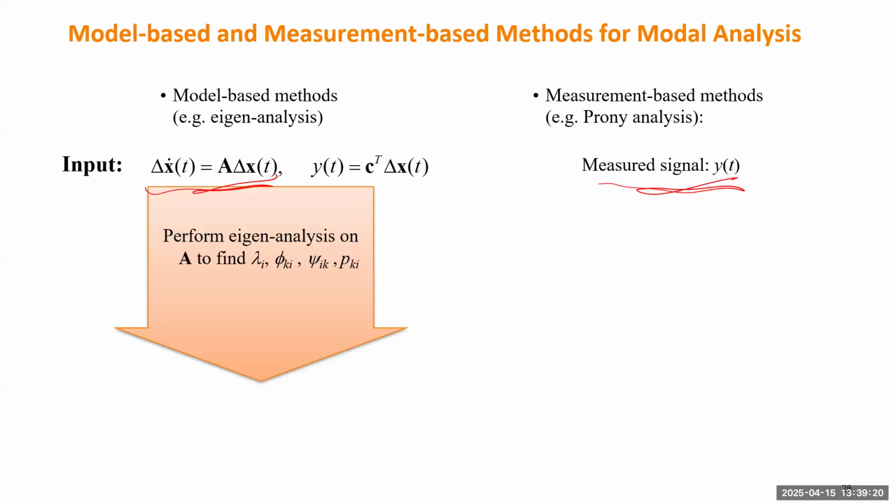For the first approach, that would be same as what we talked about. We find eigenvalues, eigenvectors, and then we calculate mode shape, compensation, and participating factors. The final answer is based on what you really want to study. So the Y here may not be a state variable. It can be voltage, current, or another variable. You really care about its oscillation.